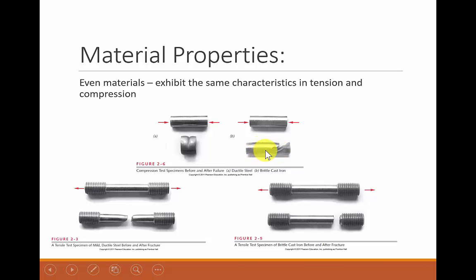And again, what's really interesting about this failure line is now this failure line seems to be on the 45 degree. So we'll spend quite a bit of time talking about failure mechanisms. But I just want you, as we're looking at these pictures, to start considering more than just that it failed or even what shape, but start thinking about maybe why it failed on 45-degree axis in compression, 90 degrees in tension. It doesn't fail in compression, although this is no longer a useful part, I don't think, and failed 45 degrees in tension.